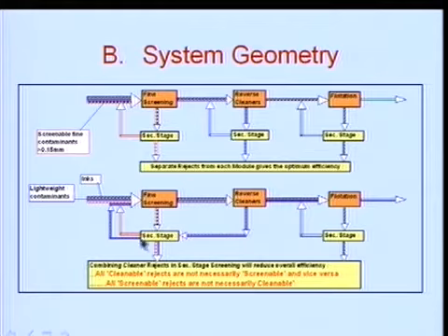So, here the second stage does not remove all of them. Some of them get removed because of the water separation or the water streams, and the rest goes back, and ultimately it does not get removed, and in the final stream we do not have just pure pulp, we have some lightweight contamination. So, the mill saved on some of the cost in trying to save on the secondary stage of the reverse cleaners, but ultimately they land up in problems because they have lightweight contamination in the final stream.